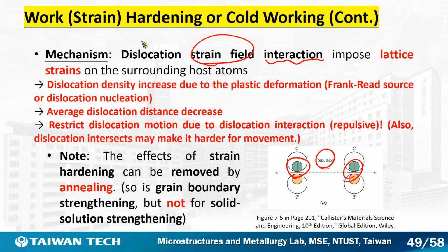When the materials experience plastic deformation, first you need to know that the dislocation density will increase due to plastic deformation. This is because when the plastic deformation occurred, the existing dislocations, the original dislocations, are not enough to induce the large plastic deformation. So dislocations must be generated during plastic deformation.